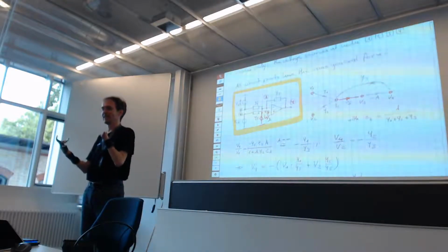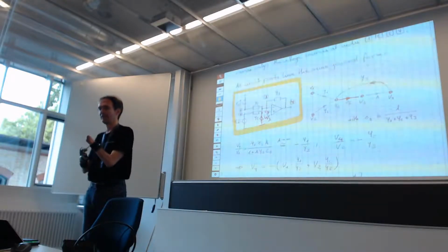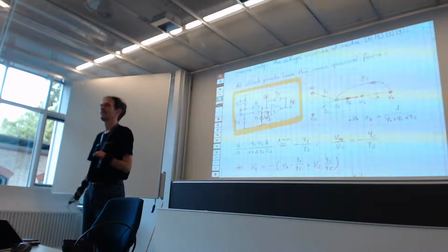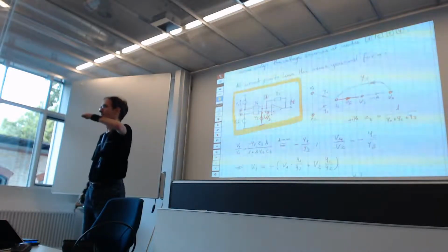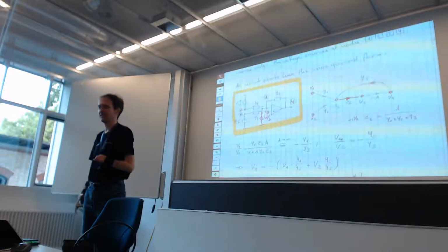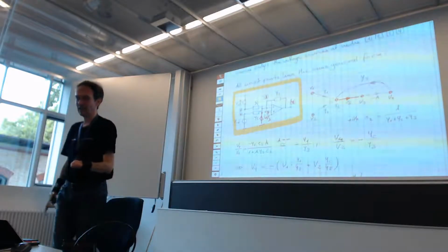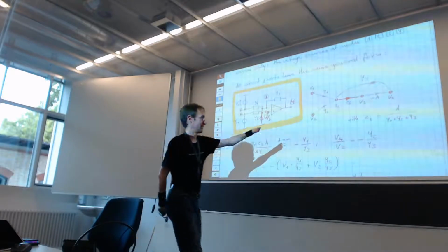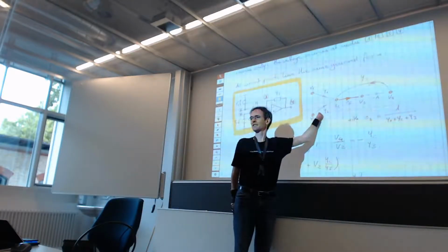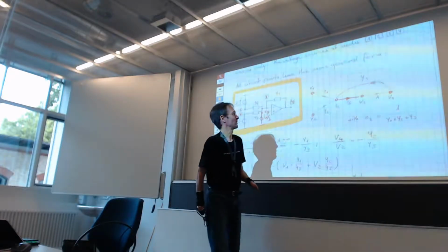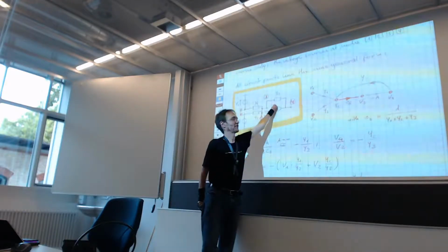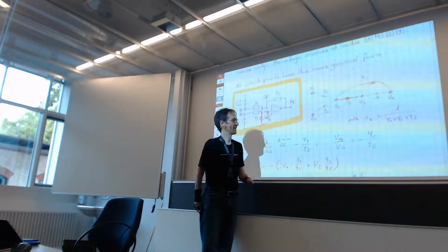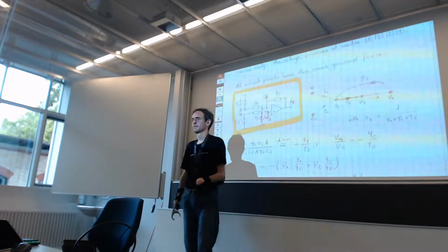So what we can now do with this circuit is the same as before. We can add things, and our adder is a Y1 or a Y2 here. And we can also see to it that it integrates. So if Y3 is just a capacitor, then I have an integrator here.